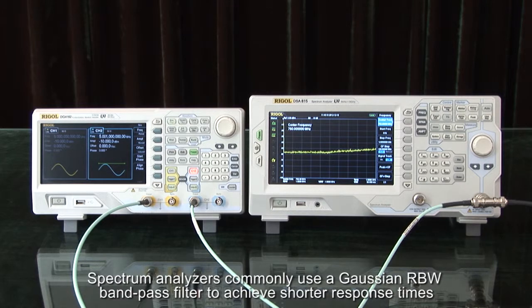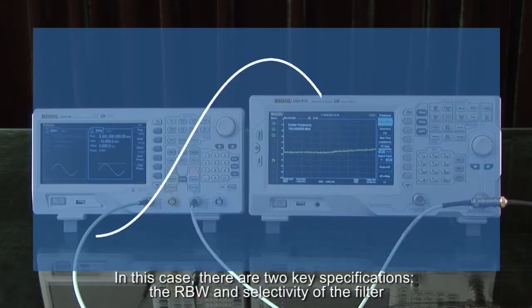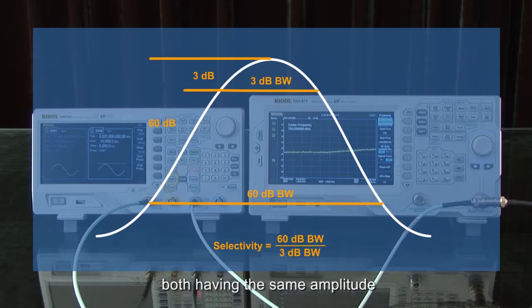Spectrum analyzers commonly use a Gaussian RBW bandpass filter to achieve short response time. In this case, there are two key specifications for the instrument: the resolution bandwidth and the selectivity of the filter. RBW is the 3 dB bandwidth that indicates the spectrum analyzer's ability to distinguish two frequencies that are near one another, both having the same amplitude.